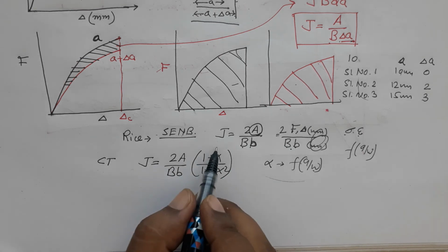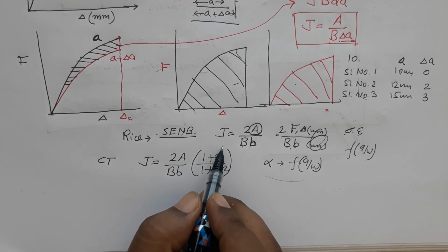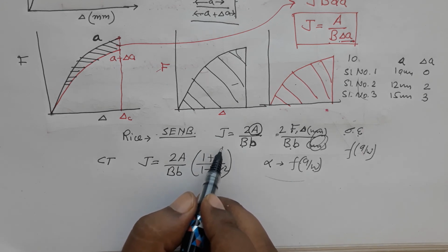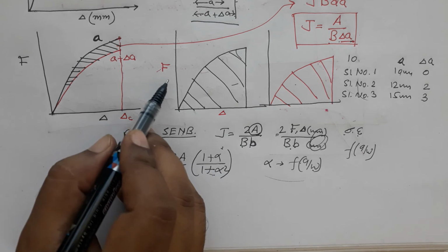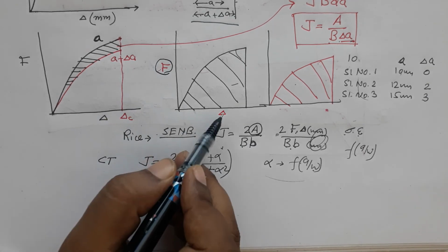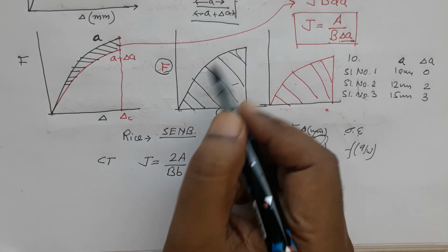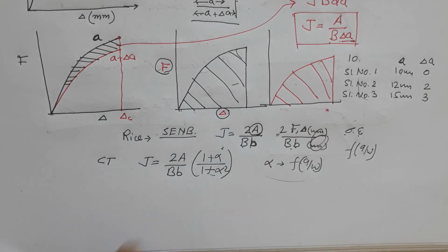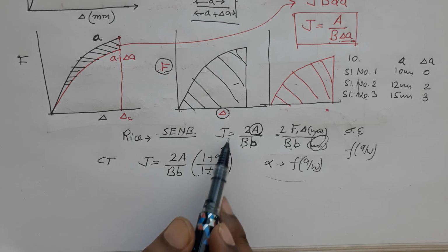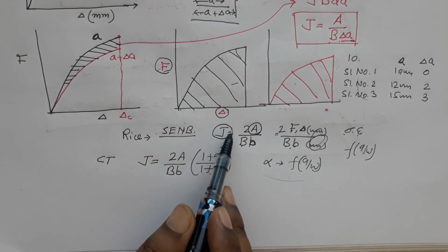What is important here is that you can find out the J integral experimentally by finding the force and displacement of the specimen. So, you get the area, and this area is telling you about the energy which is consumed in deforming this material. Okay. So, that is how you calculate the energy release rate.